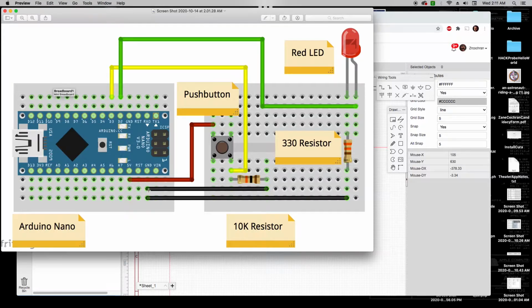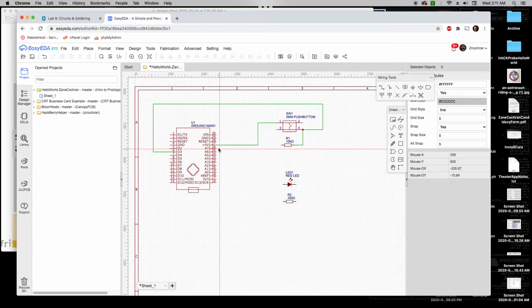and that wire, if we trace it back, goes to ground. So let's see if we can connect that other end of the resistor up to ground. So looks like I've got a ground here and a ground here. Either one is okay. I'm going to come over to this ground here, and I'm going to be kind of careful. Again, it's okay that in the schematic view that these wires sort of cross over. These aren't connected. But I do want to make sure that I get over to the ground and that things look pretty clear. So it seems like we might be able to trace this pathway pretty well.